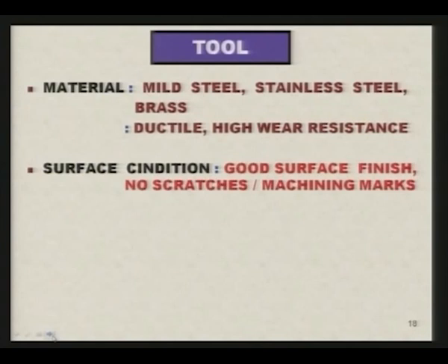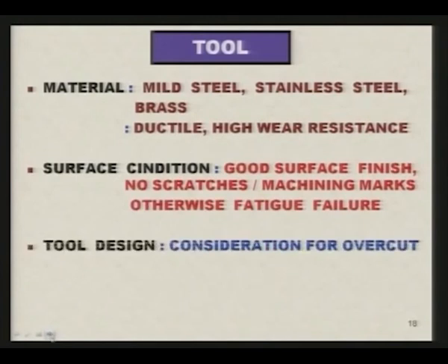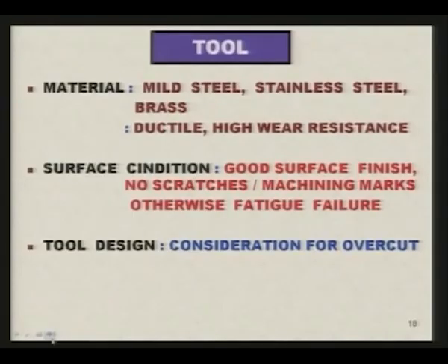As far as surface conditions are concerned, it should have good surface finish, there should be no scratches or machining marks on the tool, otherwise they will be reflected on the workpiece as well as fatigue failure of the tool will take place, because the tool is subjected to very high frequency load changing. So, fatigue failure of the tool may take place if it has certain scratches or machining marks left over there.